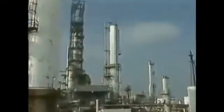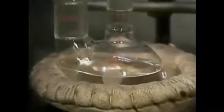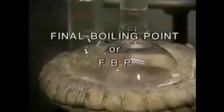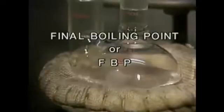The term boiling point refers to the temperature at which a liquid boils at a given pressure. But in the context of distillation, there is more than one boiling point. That's because the liquid being distilled is a mixture of two or more liquids, each of which has a characteristic boiling point. Because each substance in a liquid mixture has its own boiling point, the mixture has a range of boiling points, which is known as the mixture's boiling range. The boiling point of the component in the mixture that boils at the lowest temperature is the mixture's initial boiling point, or IBP. The mixture's final boiling point, or FBP, is the temperature at which the component that has the highest boiling point boils.